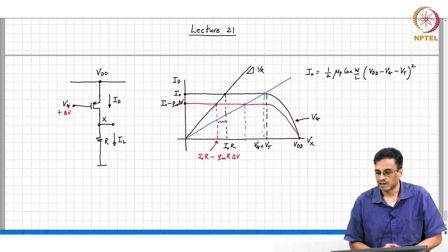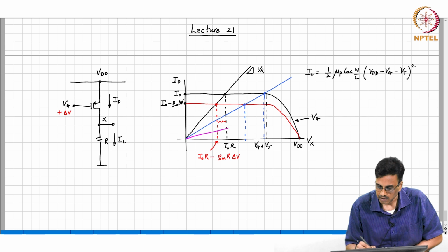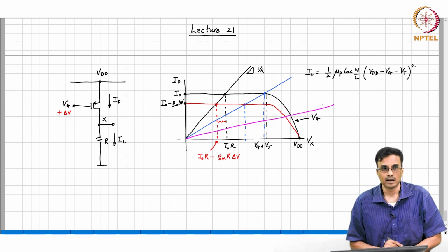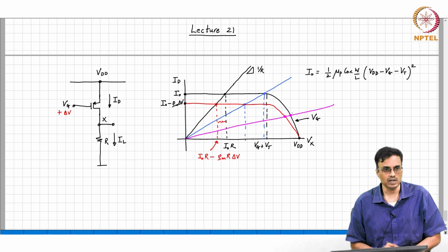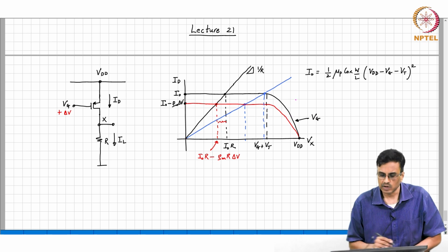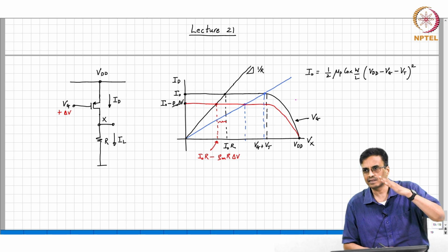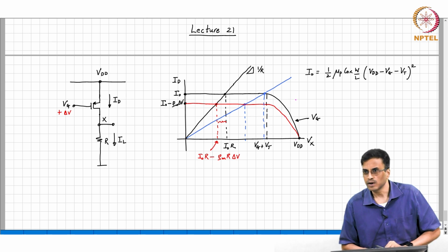The transistor will go into the linear region, and you end up with this situation, where, as you can see visually, the transistor has gone into the triode region, and the incremental gain has reduced. All right. So, as you can see, the best bet for you is to make the resistor large enough so that the transistor is operating at the edge of saturation.